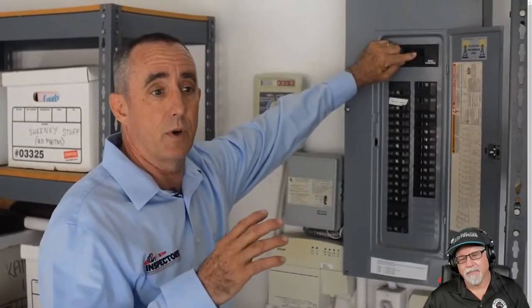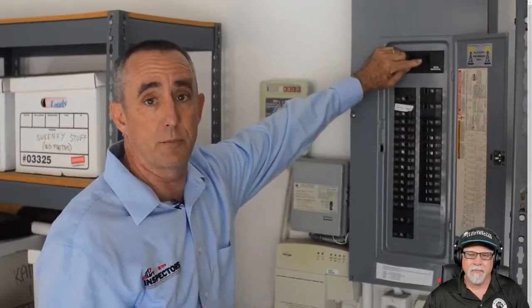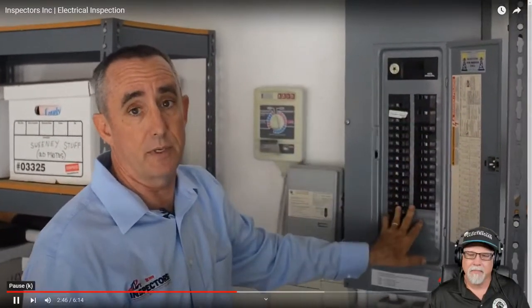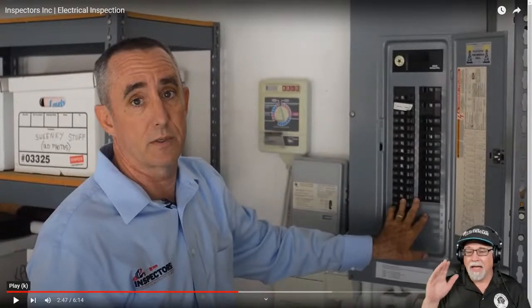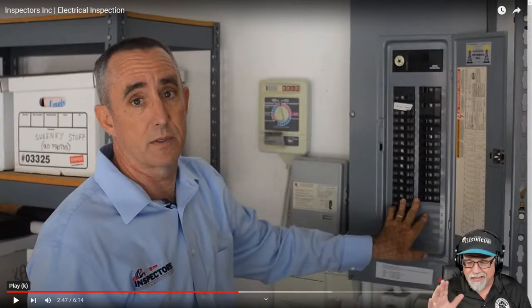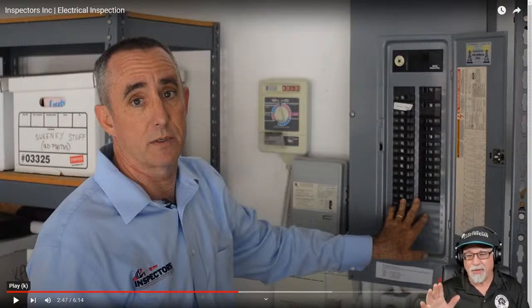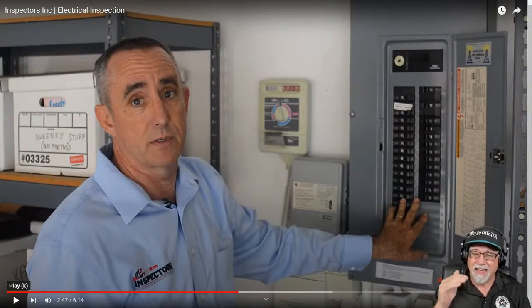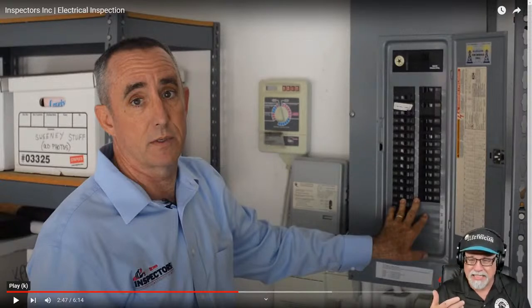If there was overcurrent, meaning the house was drawing too much electricity for any reason at all, the main breaker would shut off by itself without tripping the individual breakers. Now, let me say something about that just so I can say it out there. If none of those individual breakers tripped, but that main breaker tripped, then that tells me that you did a very poor load calculation. I'm just saying. Because if you're not exceeding the ratings of these individual circuits and they're not tripping their overcurrent device, but you're blowing a main, then somebody did not do a calculation.